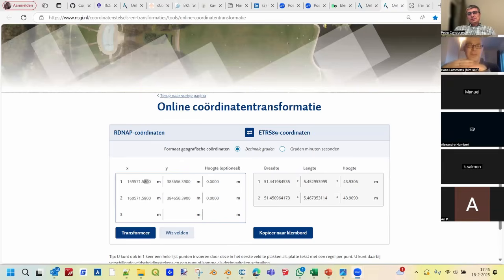I think the Building Smart Institute came to the realization that IFC 2x3 is not really that smart for georeferencing, to be honest, because with lat long and degrees, seconds, that's not the way we work in the building industry. We have to calculate it. We have to use X and Y values, and we have to use rotation. So that's why it's in IFC 4. I think it works.